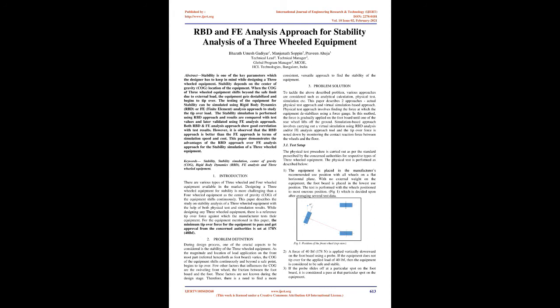While designing any three-wheeled equipment, there is a reference tip-over force against which the manufacturer tests their equipment. For the equipment mentioned in this paper, the minimum tip-over force for the equipment to pass and get approval from the concerned authorities is set at 178 N, 40 lbf. Consistent, versatile approach to find the stability of the equipment.